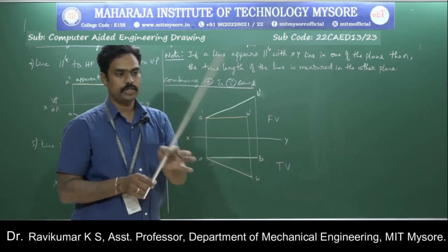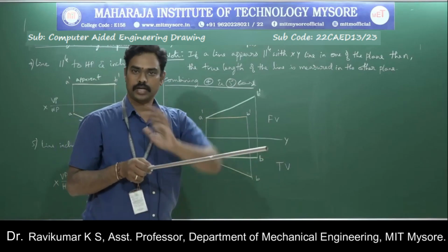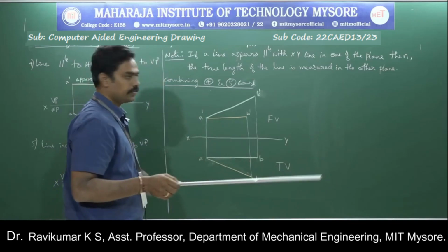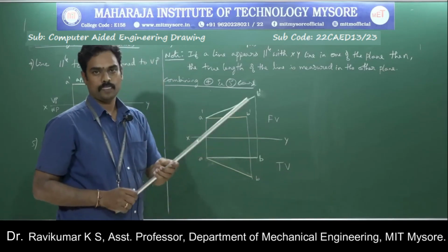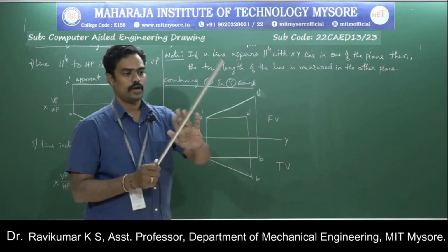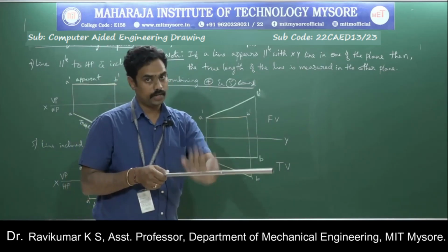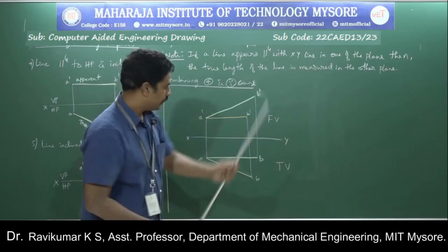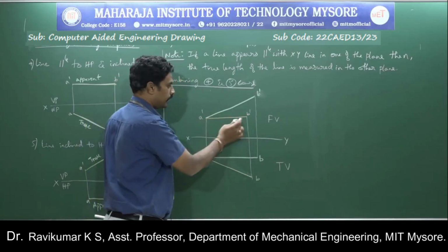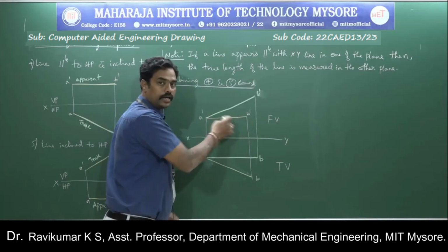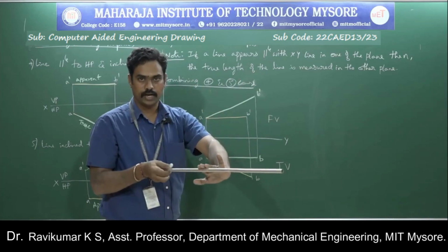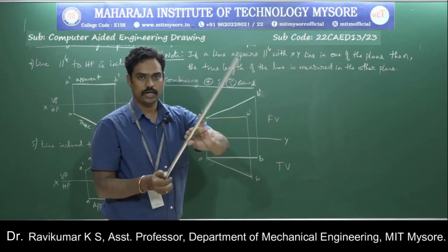So this is the concept. Just rotate the line, take off the inclination, reduce to either the fourth case or the fifth case, and get the views. Now here, what I have done is taken off the inclination to make it parallel. That means if A dash B dash is parallel now, earlier it was inclined. I have made it parallel.